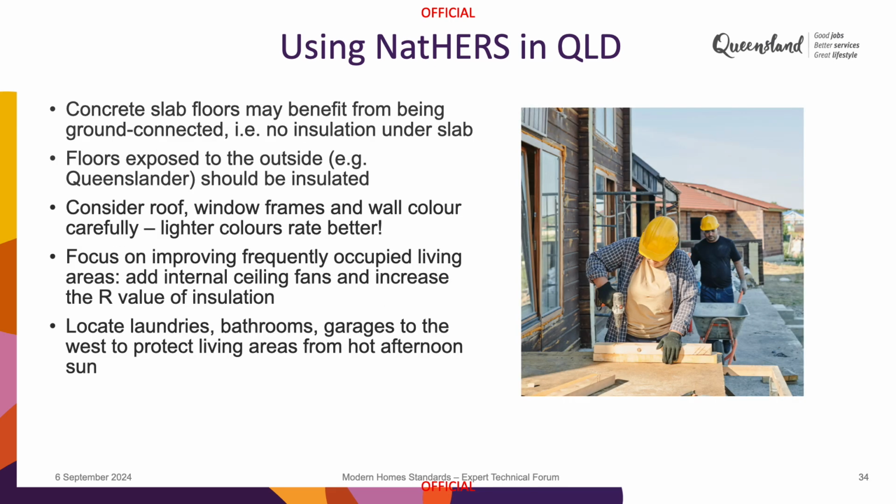Back to Anthony's point about seeing a little bit more concrete slab floor on ground, that connection to the ground is really important in terms of the breathability of the home in the summers. And as I mentioned before, the ventilation and air movement is critical also for Queensland's warm climate. So having windows that are able to be opened and not having high solar heat gain coefficients in your glazing, these things can make a big difference to thermal star rating.